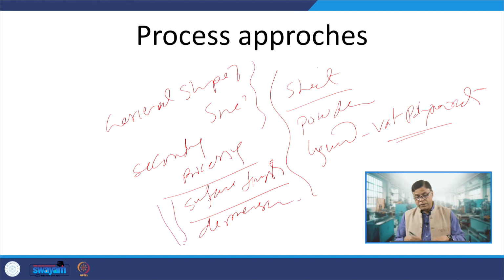So, the products made using additive manufacturing are close to the desired one in terms of size and shape, but to get final products which can directly be used for engineering applications and effective performance, the additively manufactured products require secondary processing to achieve the desired dimensional control and surface finish.